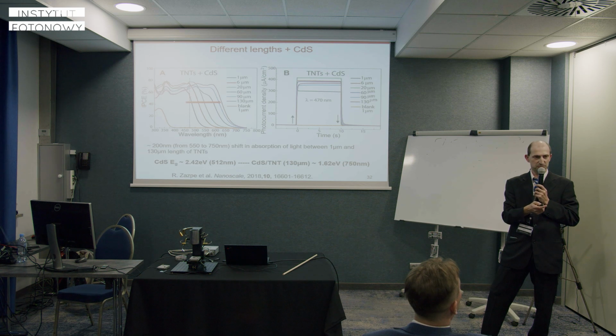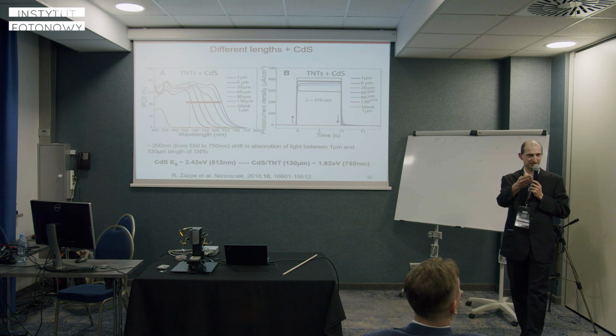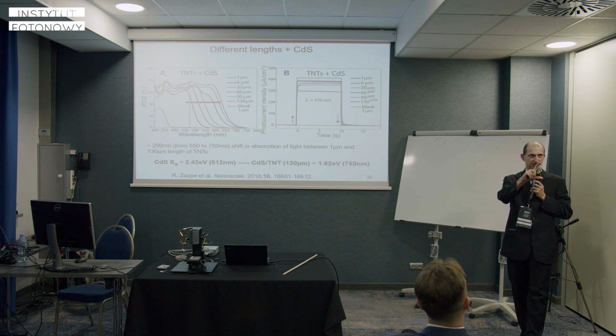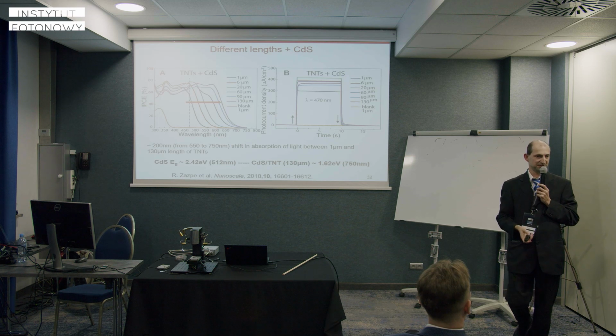So that's the reason why I try to just remove the bottom part. Yeah, that might be the reason why we cannot do spin coating, for example. This is the same story actually. We can do the outer part, but not the interior. If you have maybe a 1 micron thick film, then you have only 200 nanometers inside. You are right actually. But the exterior works perfectly, because it's the same as porous material.